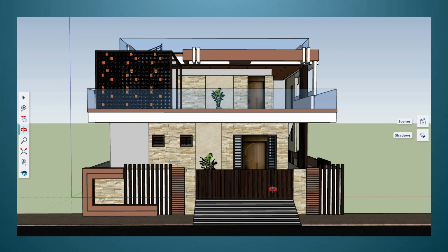The first thing is that the materials should be in the SketchUp file itself. So I have placed my materials in my SketchUp file so that when I take the screenshot, it provides proper materials in the image itself, like in my source image. Second, the glass opacity should be properly set. In my image, you can see the balcony and the roof have proper glass opacity. The third element I am going to focus on is that the road and footpath should be properly placed. Otherwise, it can't understand where things need to be placed.